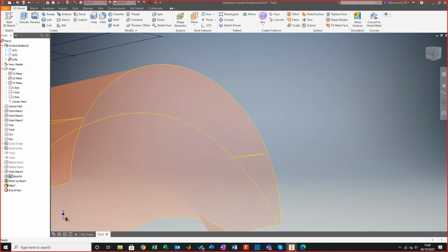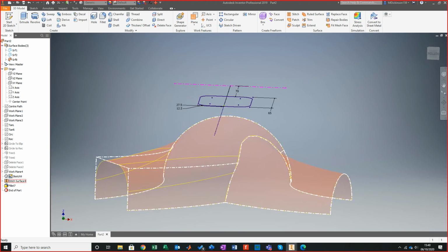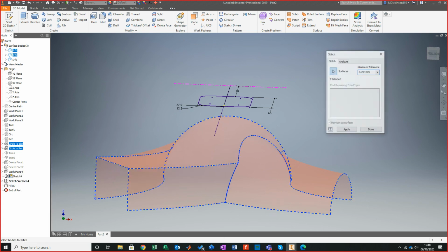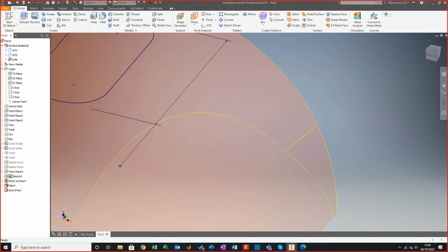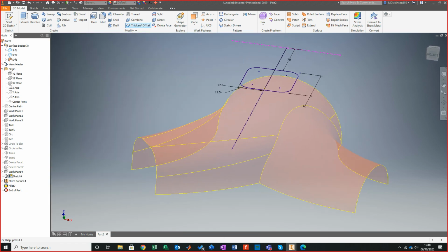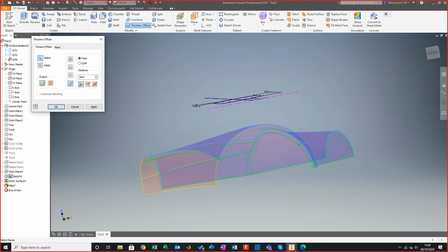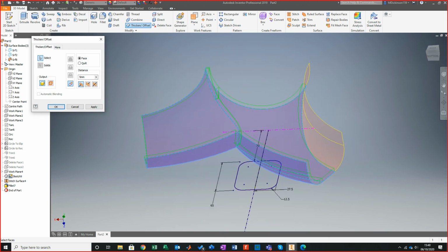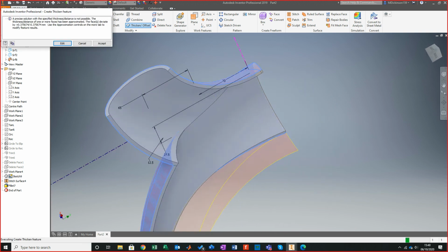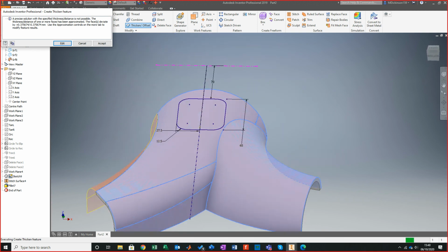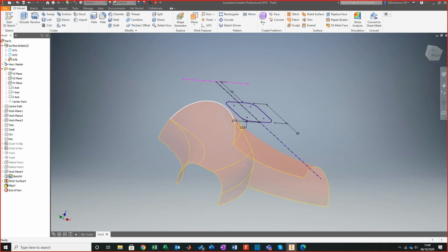Oh, look at that. So let me just go back to this stitch, edit definition, maintain as a surface. It's almost like it didn't stitch it. So let me just thicken that. So take it out to the 5mm thickness, and then click OK. Now that brought it in, but that's without the 55. So yeah, that's fine. It's just because it's complaining at the back end.